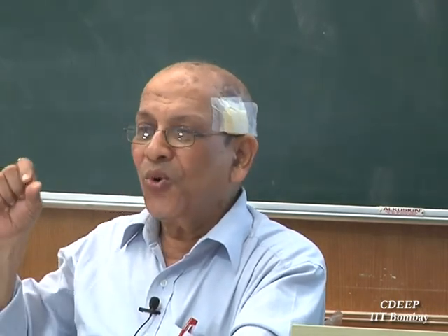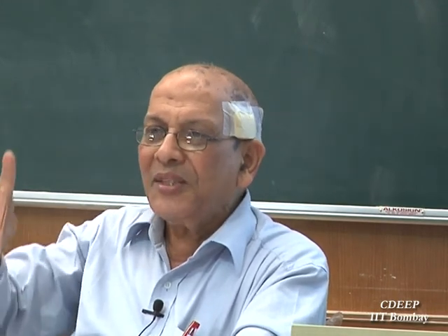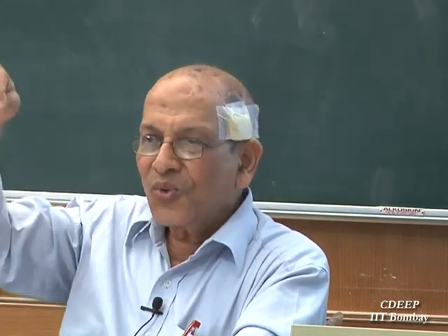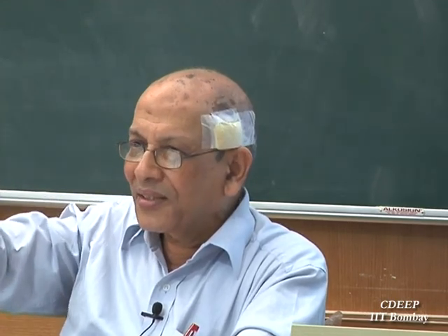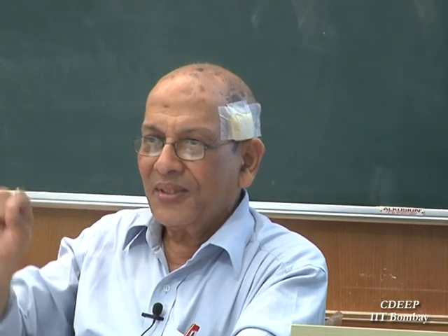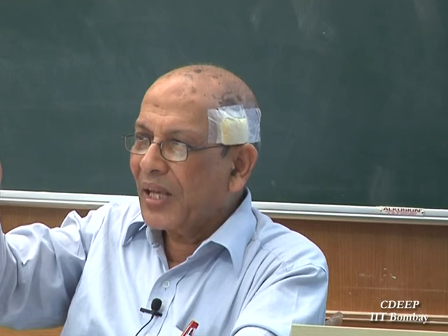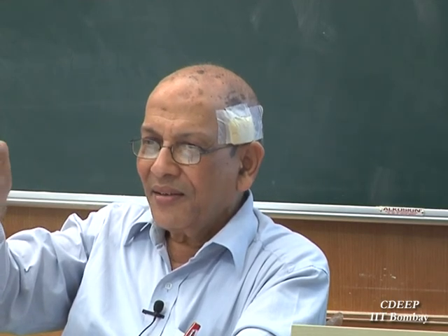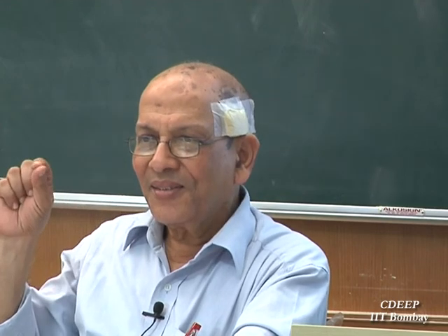Now you can still load, because that has become plastic, but the inside of the beam is still elastic. So load it further. Now plasticity will start entering through the depth from the outer edges, till the entire cross section becomes plastic.